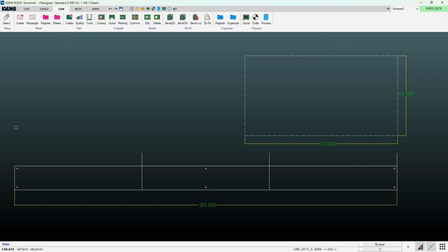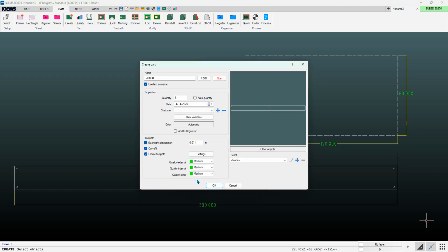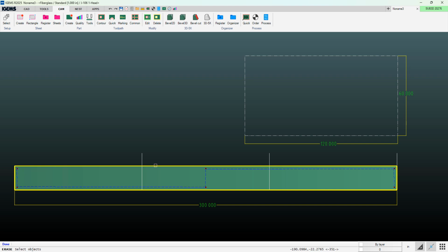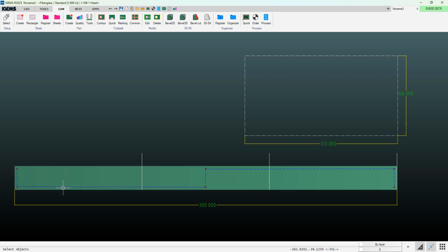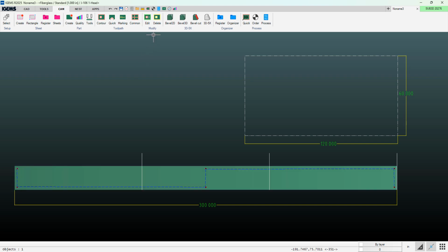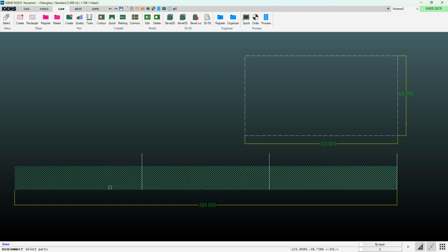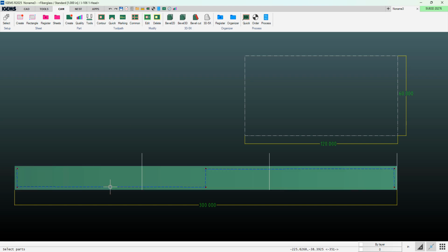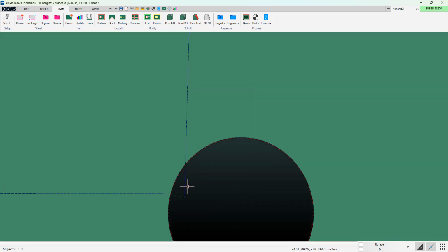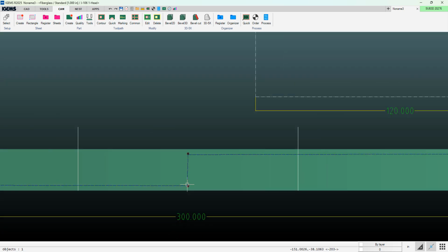And we'll go ahead and create our parts. We'll create the tool path, but then we're going to delete this outside cutoff of here. And then we're going to disconnect this tool path. Right now it's connected to the part. Go to my Modify submenu, Disconnect. Click somewhere on that tool path, hit Enter, and now when I click on that rapid line, we see that this tool path is now disconnected from the part, which gives us some more capabilities.